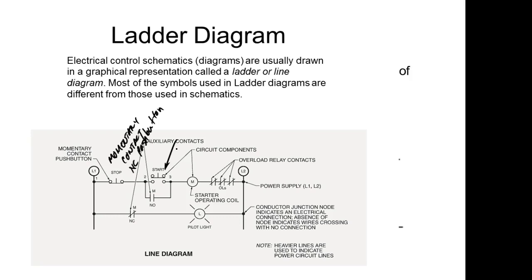From the source to the load. So eventually every conductor is going to come to an end. The technique of bringing a conductor to an end we call termination. Where we make the connection are called terminals. So anytime you see that clear dot, it means that's a terminal, right? Which means that's where we would connect to this device.